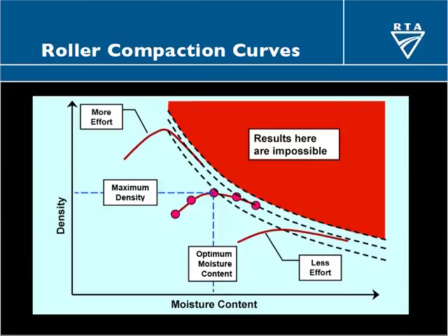You'll find that the optimum moisture content, maximum density lies on something like the 5% air voids curve, and that the wet leg of those curves on the increasing moisture content side will start to run parallel to the 2% air voids curve. And that reflects the fact that for any compactive effort, it's really difficult to squeeze that last couple of percent of air out of it.